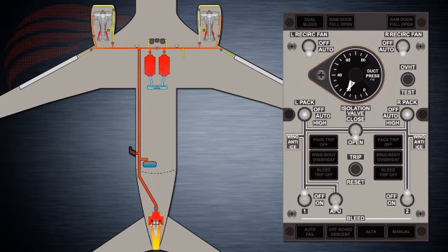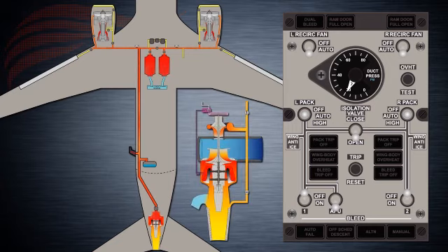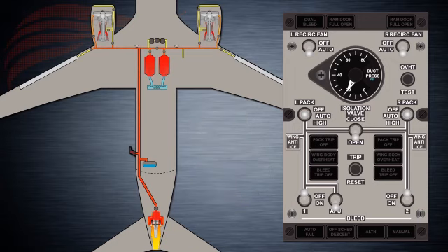In case the pressure regulating function of the APU fails and excessive bleed air is ducted into the pneumatic manifold, an APU pressure relief valve protects the pneumatic manifold duct from rupturing by relieving bleed air overpressure. Any pressure under 75 psi is normal. When the pressure exceeds this value, the APU pressure relief valve opens and only closes back once pressure has dropped below 65 psi. The supply of APU bleed air is not directly controllable.